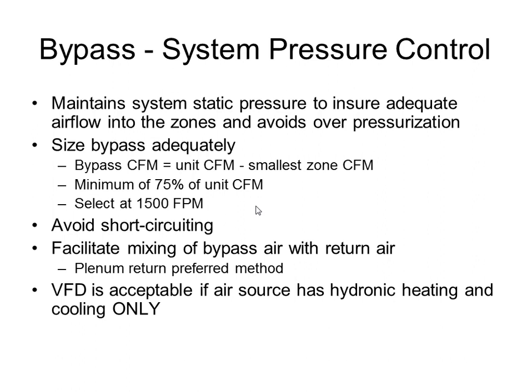This is going to affect your supply air temperature. Say, for instance, if you're in heating mode and you're discharging 120-degree air, if you're bypassing a large quantity of that air, then that's going to go directly back to your unit and then sent back through the heat exchanger, and that temperature is actually going to increase your supply air temperature. So if your bypass is not sized properly or located properly, you could be short-circuiting and then either increasing your supply air temperature in heat mode or decreasing your supply air temperature in cooling mode, and that causes problems. You can start to heat, freeze, or overheat coils, and you can also dump or stratify air into the spaces, which is something you don't want to do.